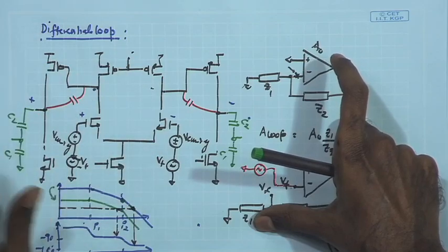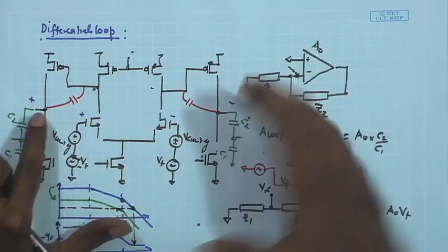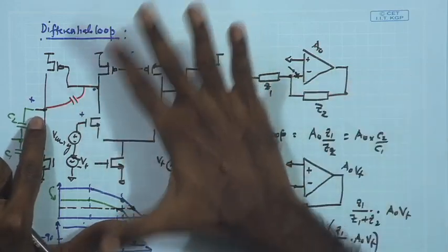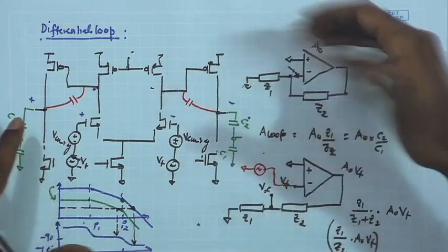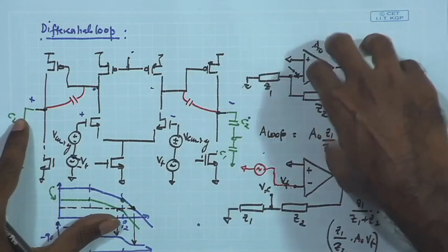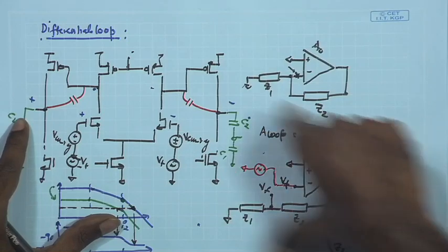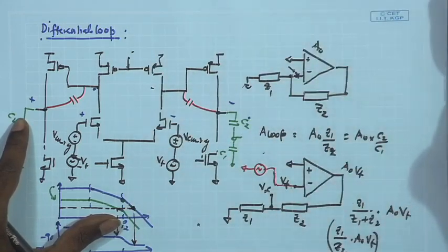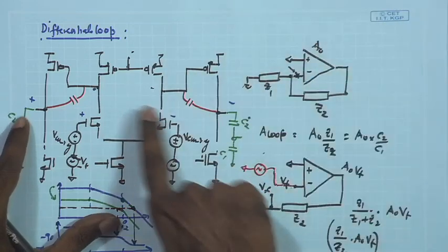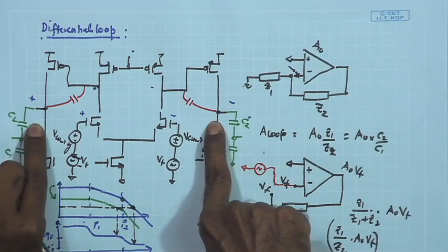This is just a DC bias point, and also here we have seen that for the combined common mode loop, if you are having a single common mode loop, we have also reduced the impedance of the common mode error amplifier by using a diode connected load, and as a result that is not going to contribute to a significant pole, assuming that whatever poles are coming from that stage are much higher than the poles at the two outputs of our main differential amplifier.